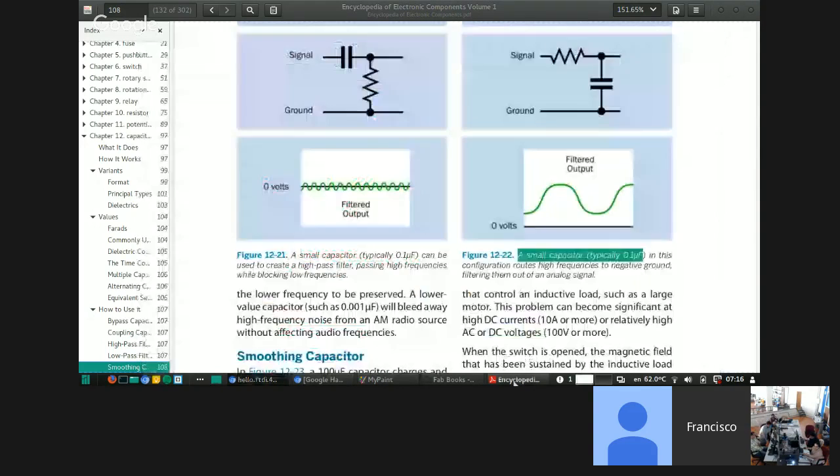See, the purpose of the resistor here is to supply the PB3 pin with the 5 volt. So it keeps the PB3, the reset pin, high all the time. But we don't want a lot of current to flow into the reset pin. So that's why we put a resistor over there. In the ideal case, we don't have to put a resistor because digital circuits shouldn't consume any power.